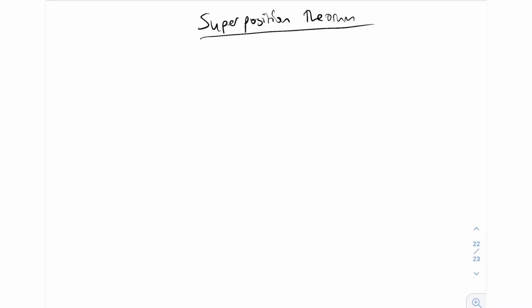Okay, so in terms of the actual definition of superposition, it has to do with a circuit that contains more than one independent source, whether it's voltage or current. So you've got obviously a battery, or a voltage source, and you've got current sources. Any circuit that has more than one of these, then what we're saying is that the response in any of the branches, meaning the currents and voltages, is equal to the algebraic sum of all of the responses caused by each individual source when it's acting alone. That's the important part. And that's obviously on the basis that all of the other sources are replaced. So that might not make any sense to you. Don't worry about it. It'll make sense when we go through the example.